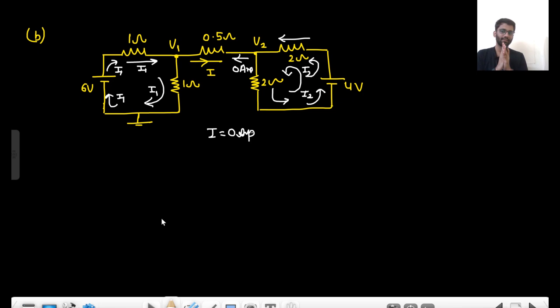What did I say here? If you go by this analogy that I1 current is given here and it is taking back the same I1 current, then you can't really say that this I1 current is flowing here. What did you do? You went to this loop. You just saw that if this is giving I2 current, this will take back I2 current. So in the complete loop, I2 current is flowing. So what did you understand by that? If the complete current I2 is flowing, that means there is no current going this way. So that means in the 0.5 ohm resistance, there is no current flowing.